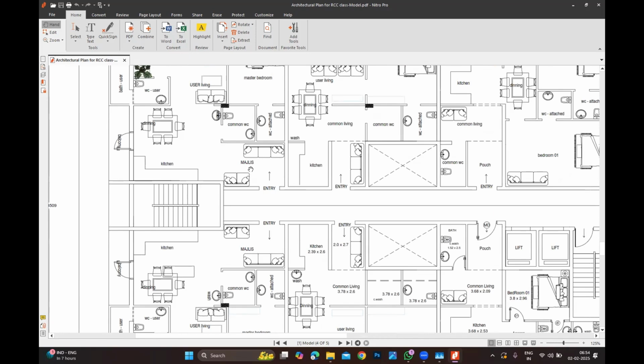Sometimes, for the cantilevers, for the balconies, or when they want to arrange any trellis or canopies, unnecessarily they will extend the slabs like 2 meters, 2.5, 3 meters. Try to look into whether it is really required. If it is not, just inform them to avoid this cantilever. These are all suggestions which you are going to give on the architecture. It is not a mandate that you need to follow 100% whatever has been there from the architectural point of view. And as structural engineers, we change the entire architecture.